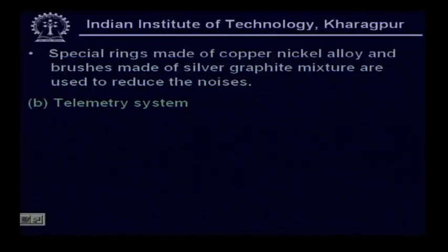Now, special rings made of copper nickel alloy and brushes made of silver graphite mixtures are used to reduce the noise. So, you have to use these different special types of slip rings, made of silver graphite mixtures, to reduce the noise.